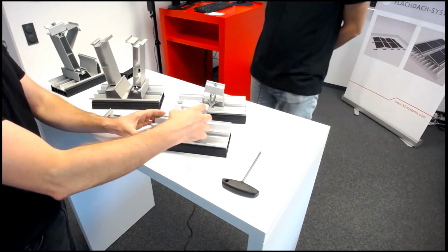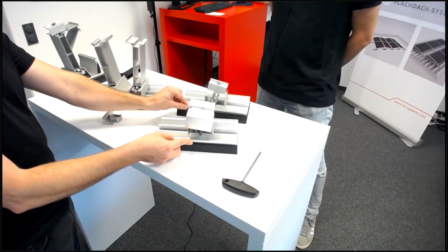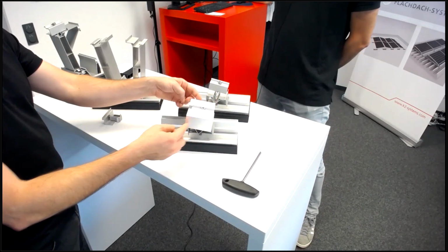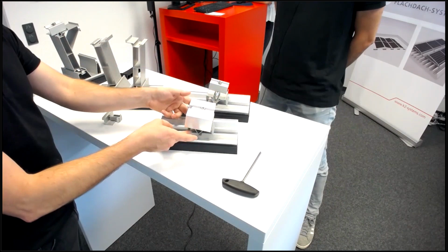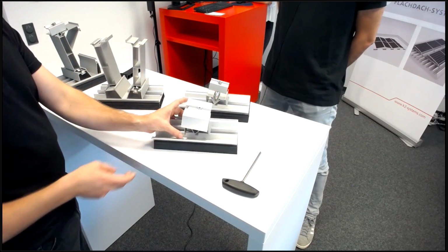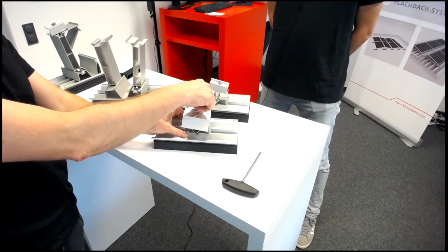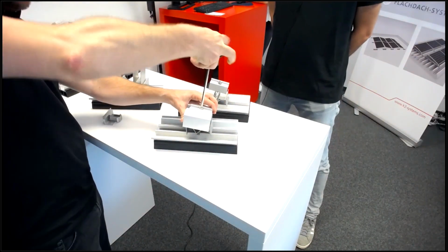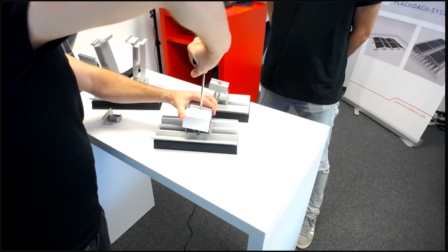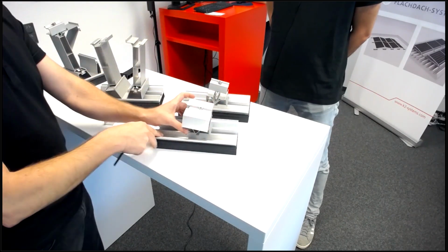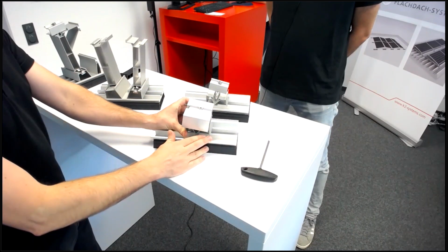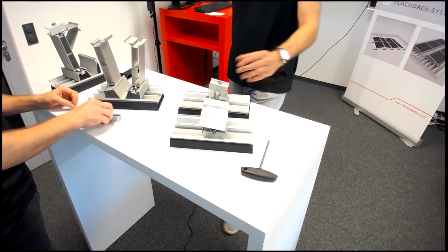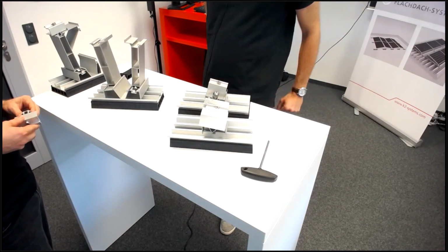We have a model prepared here. These two tubes simulate your module frame, and here you see one of our middle clamps. And now, as long as the clamp is not fixed yet, you can move the part, but as soon as I fix the screw and so fix the modules, this is stable without any additional screw. Yeah, so basically the module clamp also has the function to stabilize the system.